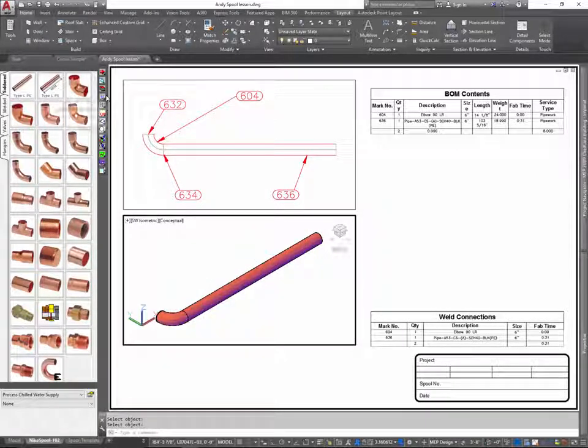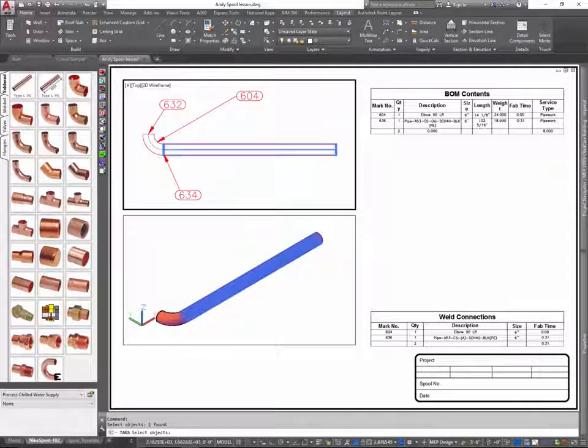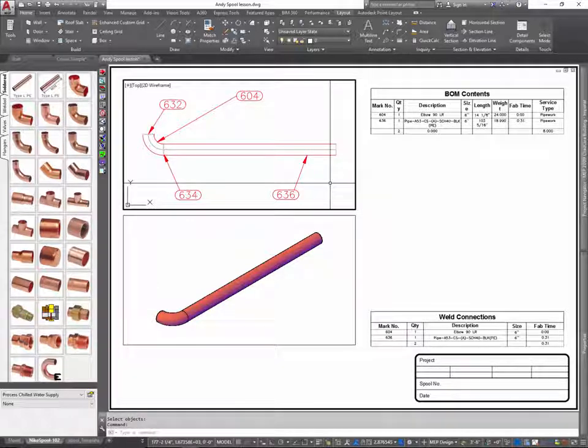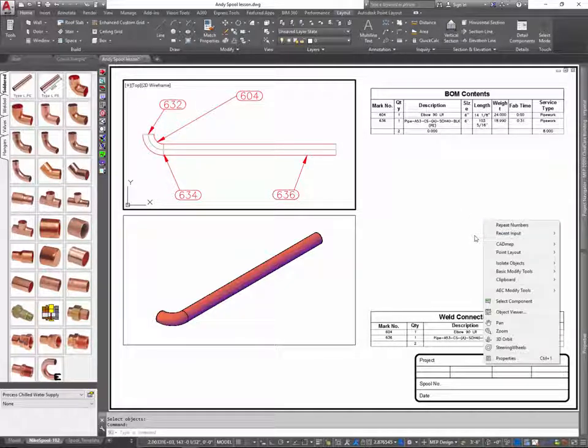And if I wanted to tag that, I could come in here and do my tagging. So here's all my tagging features. Here's the number, and if I wanted to select just one of these objects and pull that out, that'll tag it on and off, as you can see. Let me put that back on in the plan view here, just so I can identify that and make sure that's on. So a couple of ways to do that. It's simple. You can use the tag feature in here, and you can hide it in that text, in that particular viewport.